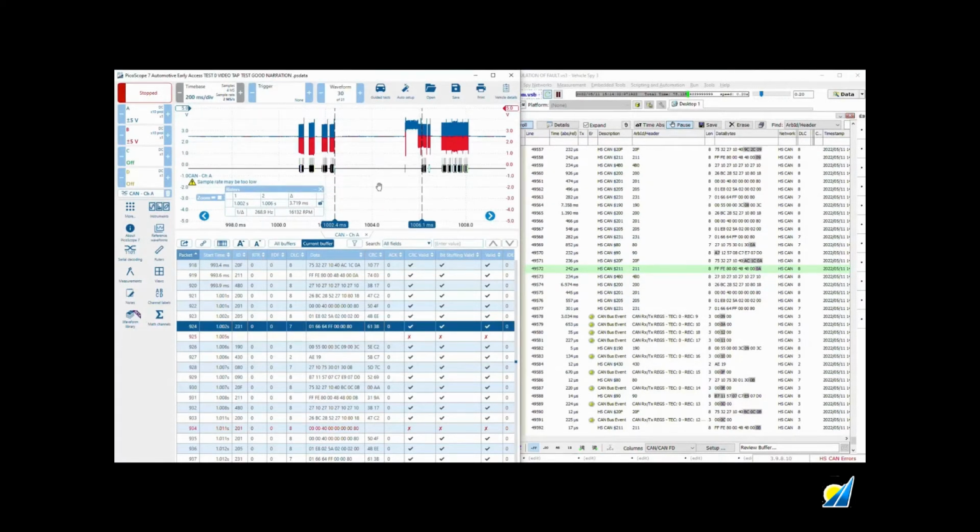So with 3.719 milliseconds between those events, let's have a look at Vehicle Spy. So there's the last successful message to ID 231. And then the next one is 190, which we've confirmed here. And in between there, then we have REC, which is receive error count. And these are being incremented up to 18, and then they start to decrement. So it appears that during that period of time, in fact 3.034, I'll say roughly about there, in that period of no transmission, it would appear that nodes are storing and recording in their respective controllers, error counts. Now we can't see that in PicoScope at that point.